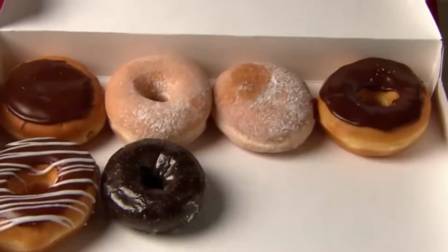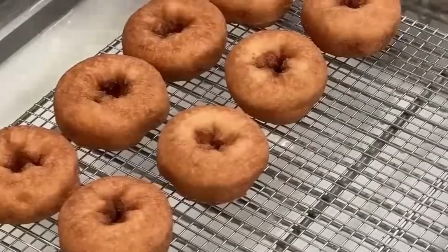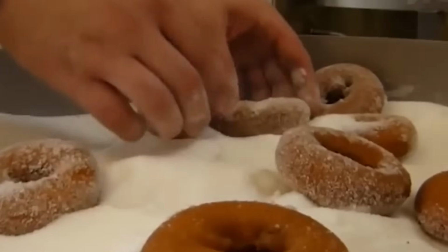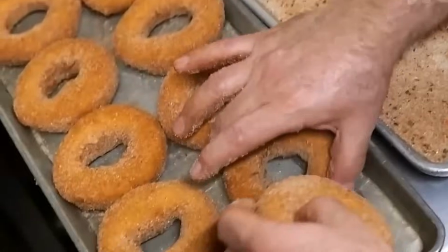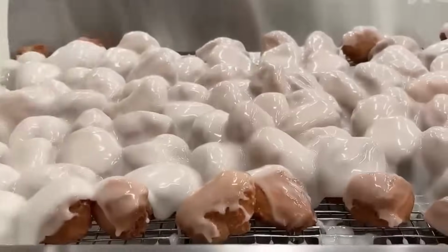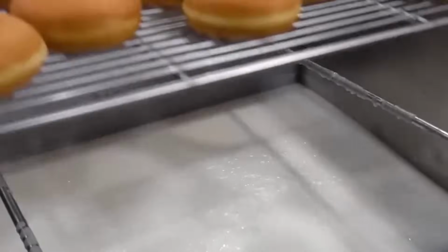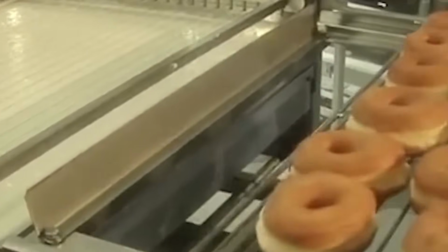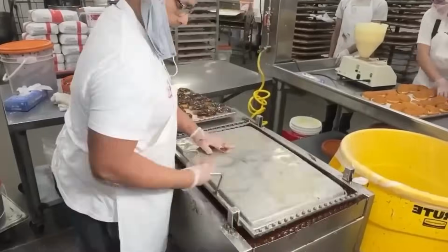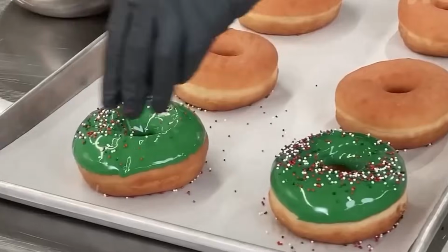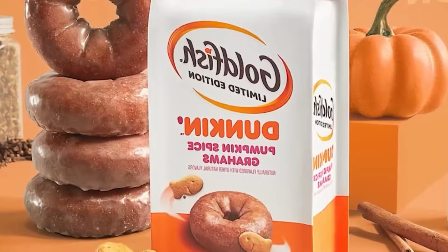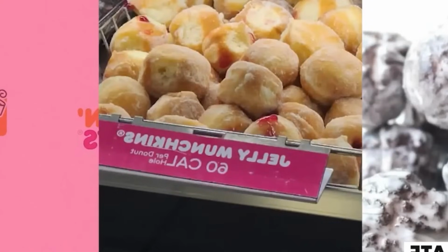The cutter contains interchangeable dies for different donut varieties, including ring shapes, filled rounds, bars, and novelty shapes. The cutting drum rotates in synchronization with the conveyor to ensure clean, high-speed cuts. Cut donuts are transferred onto wire mesh proofing trays by vacuum-assisted pick-and-place systems. The trays are automatically stacked into a multi-tiered conveyor rack that moves through a temperature and humidity-controlled proofing chamber.